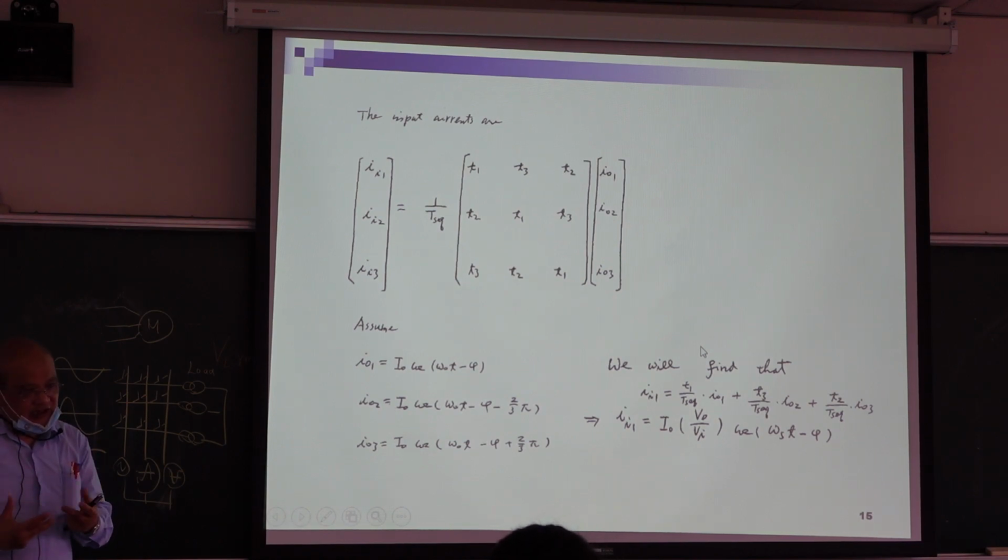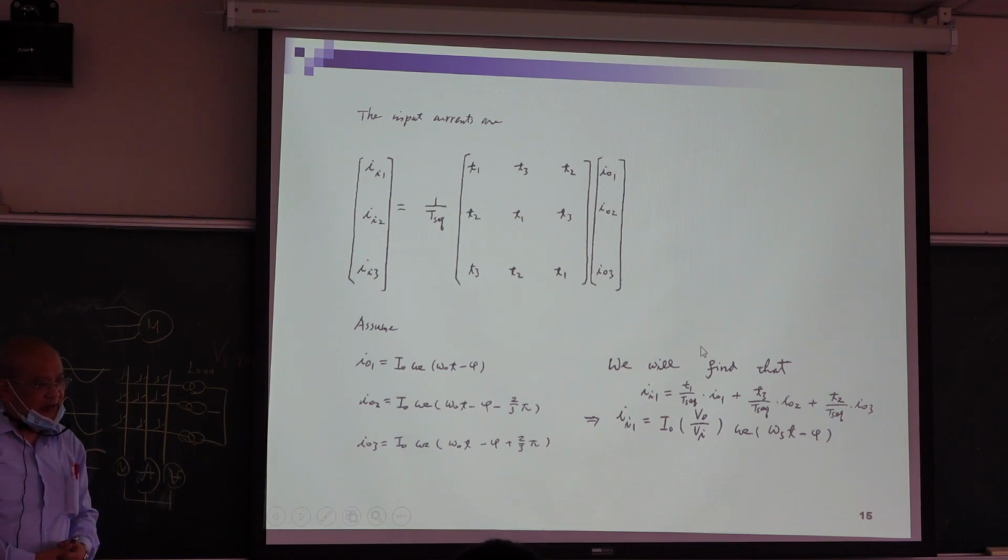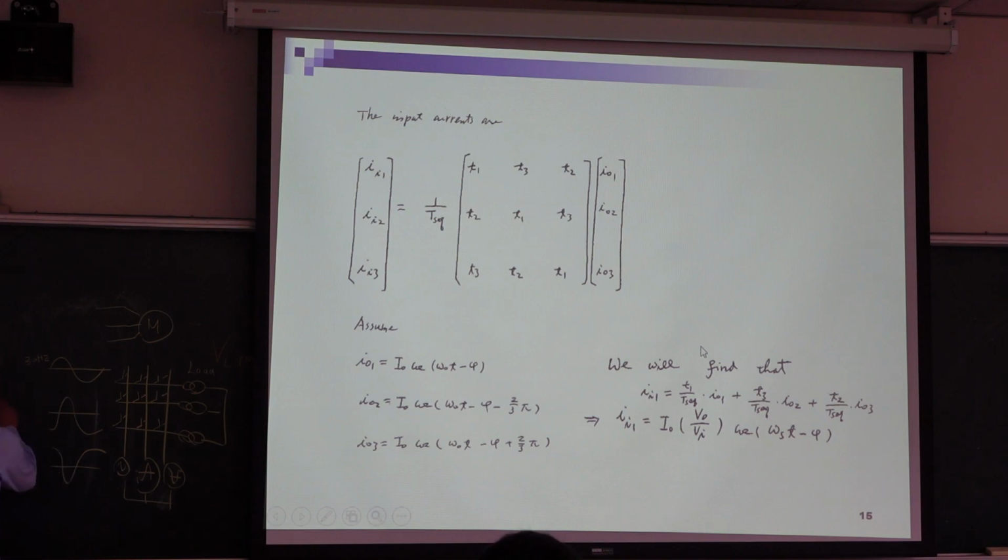If you think it is leading, please raise your hand. If you think it is lagging, please raise your hand. It should be lagging, right? Because of inductance, so you have V, you have Z. Then this is I, so I lags by theta, right? So you have voltage here, you have an inductor, so the current should lag.